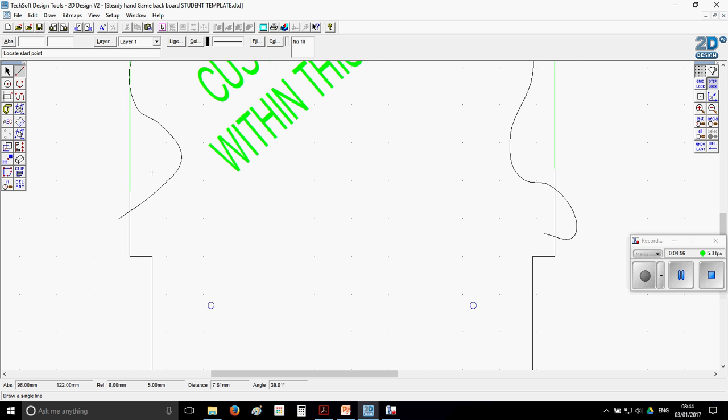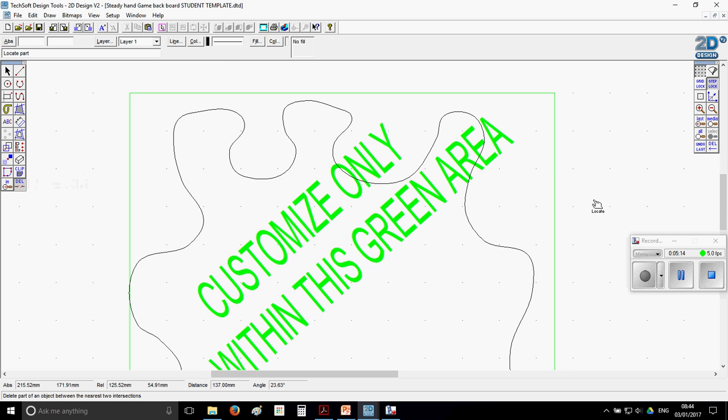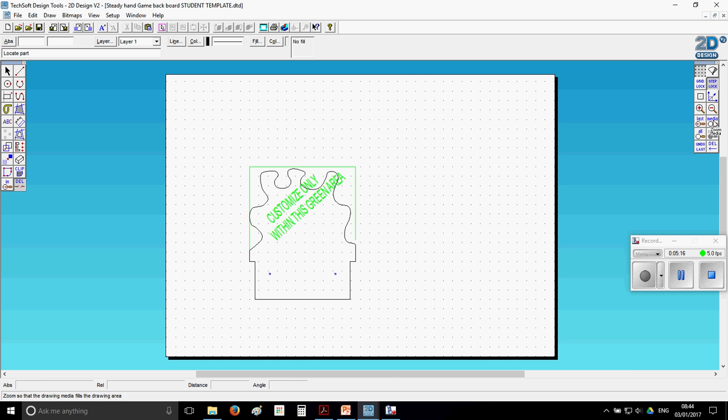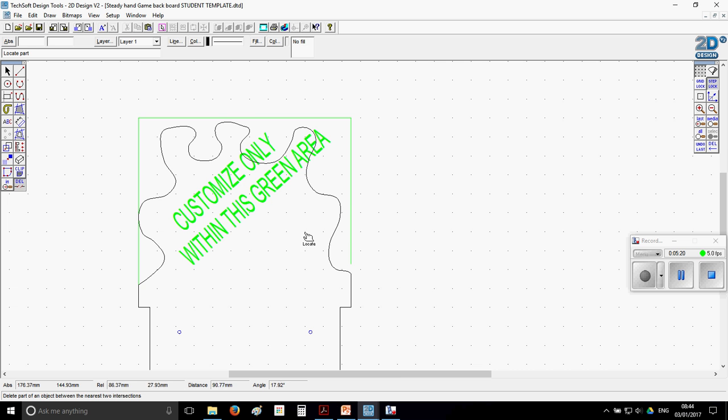The next tool you want to use, it's very useful, to get rid of that sticky out bit is under here. So you go to delete, but hold down the button on your mouse and select the second one, delete part of an object. This allows you to snip and snip. You can see there where lines overlap, like so. Sometimes you have to click a couple of times, right? So that's how I could make my outline and how I could make it join up. Right, that's one way of doing an outline. I'll just delete that now.